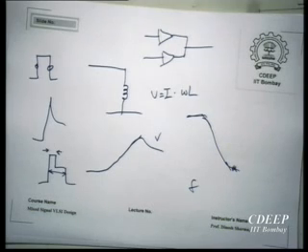So it has to keep track with your circuits, and this design either with this or with that is quite good enough for that. It turns out that if you are looking for low power, low speed, then correcting at the receiver is better because it saves power. You don't require these high current dumps. If you are looking for high speed circuitry, then rather than doing inductive input and then big amplification, that is not better. It is better to have an overdrive transmitter. So there is a difference and there are clear areas of optimization.